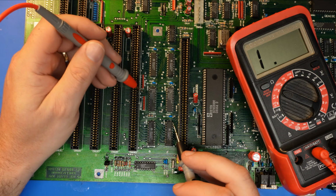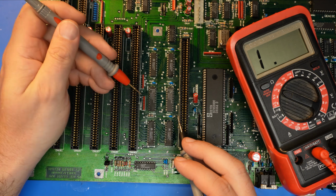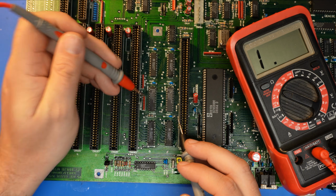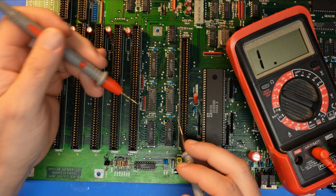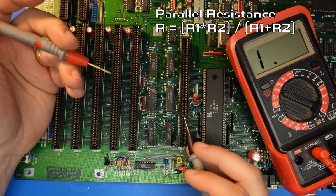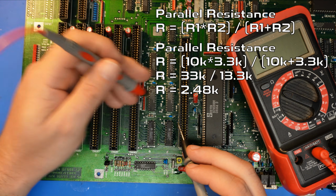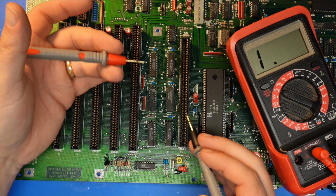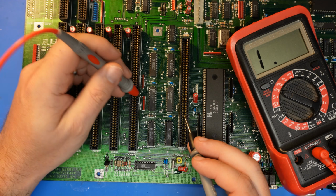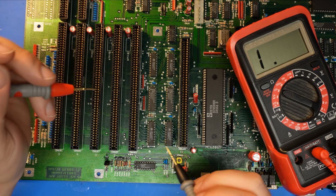So perhaps it's a case that that pull-up wasn't strong enough at 10k, and by fitting the 3.3k, well, you're fitting that in parallel with the 10k pull-up, and a 10k and a 3.3k in parallel, if you're going through the calculation for that, it comes out at about 2.5k. So definitely strengthening that pull-up, although ultimately it seems that 1k on all those pull-ups provided by both those resistor packs, that's the ultimate fix for that. So I think we will just ignore that one.